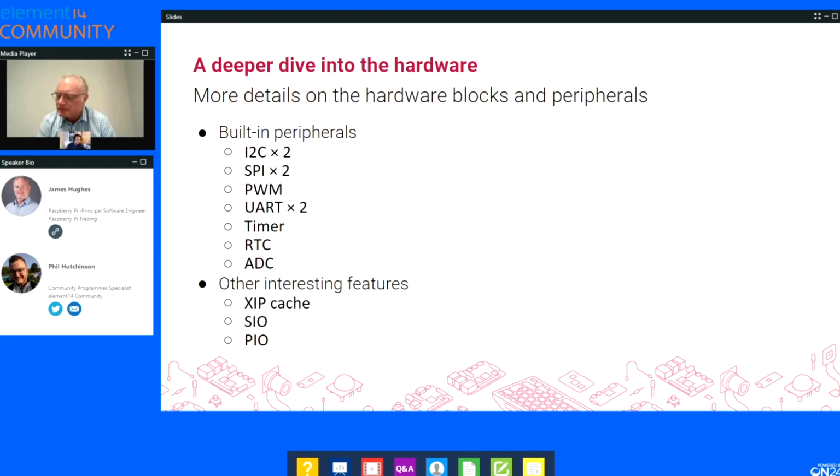There's quite a few people interested in the ADC. Sorry to cut you off there. There's a little bit of delay between us. So I believe you might have just covered that, but Susan asks, has the ADC data reading spike issue been addressed? I believe that may be what you've just been referencing. Yes, that is exactly the case. We haven't respun the chip just to change that. It's a very expensive business to respin a chip like this. So at the moment, that errata is still present in the chip.